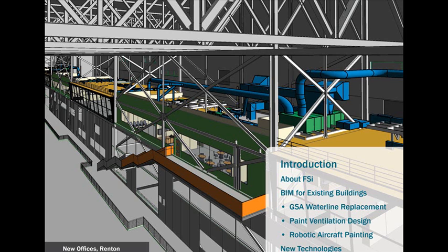The question is, did we spend the time to input all the detailed information, airflows, the voltages, and so on. And we didn't spend that time on the stuff that was already there. We spent that time on the stuff that we were installing. If it was new, if we were touching it, we had it in there so that you could click on a duct and find out what the static pressure needed to be to get the air from wherever you started to there. And that worked great in a lot of cases. The tap fittings and screws mess that all up. So, anyway, you're back to the old pen and paper. Yeah, and on stuff like that, it's almost quicker than to go in there and try to mess with some of that stuff. So, yeah, we didn't do that.